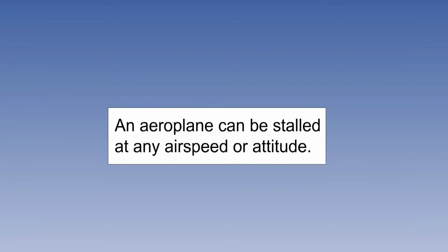It is important to remember that the angle of attack is the angle between the chord line and the relative airflow. Therefore, if the angle of attack is increased up to or beyond the critical angle, an aeroplane can be stalled at any airspeed or flight attitude.